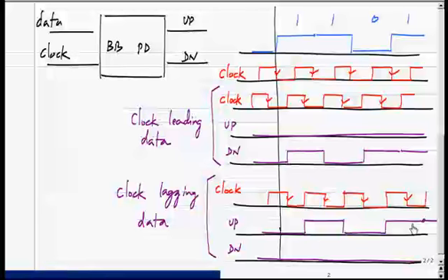So to do that, let's first examine what happens to the output of the VCO in the analog loop that we have. After that, we can see what to do digitally. I'll draw the charge pump and the analog loop filter here. So the charge pump gets inputs up and down.